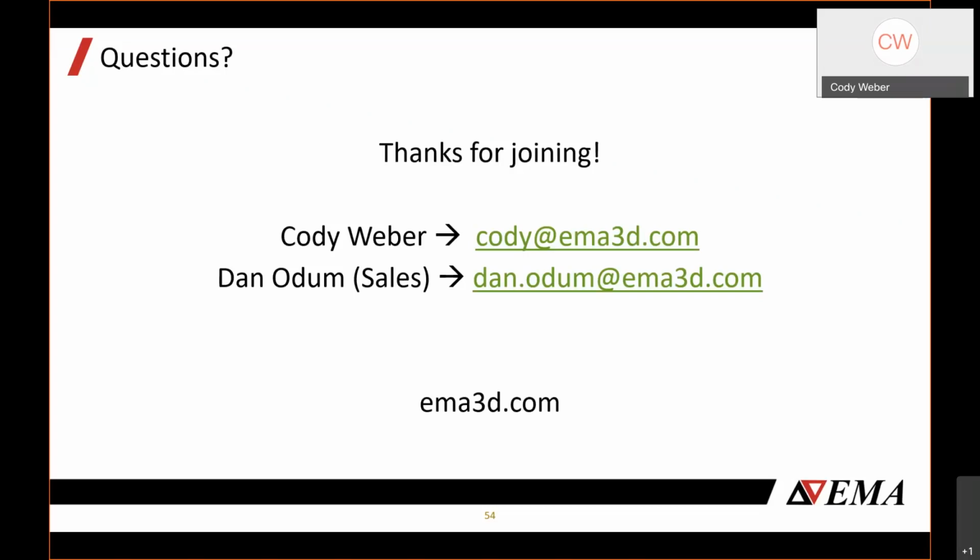Okay, and we did just get another question from Chuang. He said, why not use worst case coupling instead of using the average spatial and 5% frequency? Is the worst case more realistic for certification? That's a very good question. Part of this should be addressed in your analysis plan. Sometimes it's no problem to use the worst case in the most severe environment that you measure or analyze, and your system level verification can go forward using those severe levels. Sometimes it's too severe and it creates problems, and then it's more meaningful to use the average values.